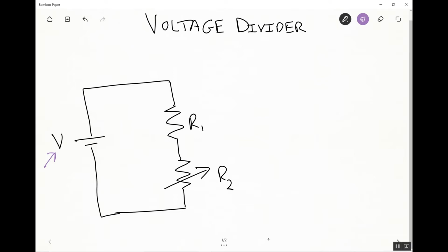So what we do is we introduce a current limiting resistor, and then all that remains to be done is to calculate how much resistance that resistor needs in order to limit the voltage to the LED to 2 volts and the current in the circuit to 20 milliamps. And we use Ohm's law and Kirchhoff's voltage law to do that. So this is a voltage divider circuit. The voltage is divided between 2 components, and we can use Kirchhoff's voltage law, that the sum of the voltage drop across those 2 components equals the total voltage in that circuit loop. And we use Ohm's law to calculate what that resistance needs to be. And in this case, it's 150 ohms.